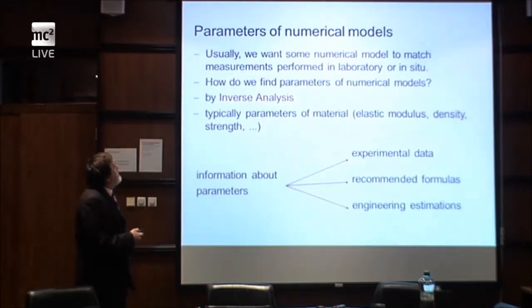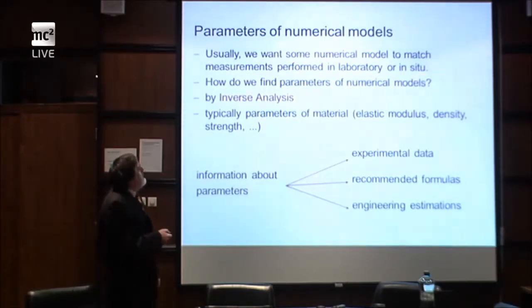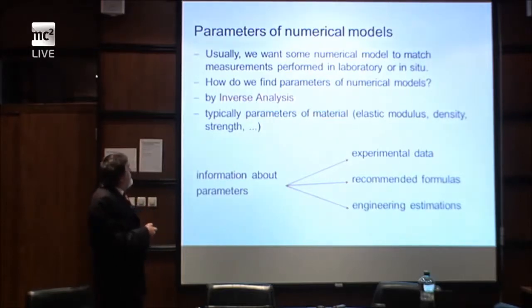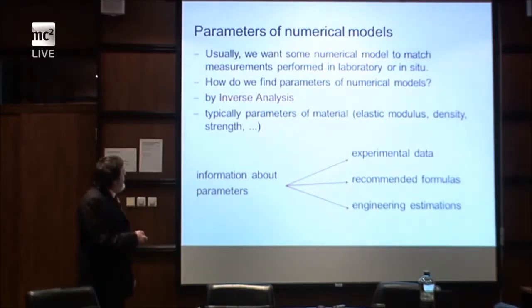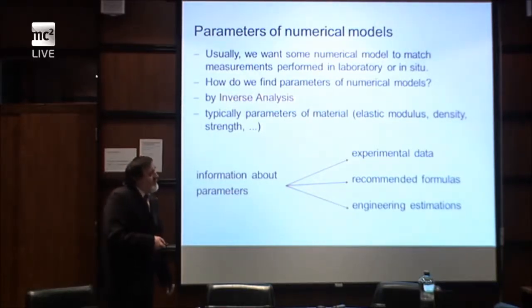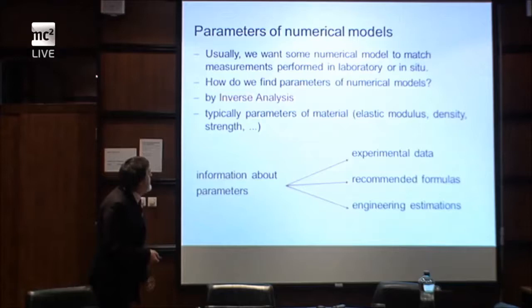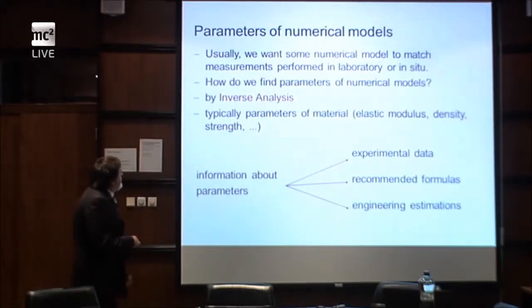Slide, parameters of numerical models. If we develop some numerical model, we usually want our numerical model to match the measurement performed in laboratory or in situ. How do we find parameters of numerical models? This is sometimes very difficult, and one option is to do it by inverse analysis. Typical parameters of materials, especially in case of concrete, are elastic modulus, fracture energy, density, strength, etc.